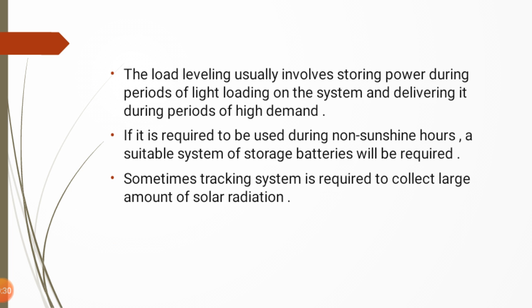Load leveling usually involves storing power during periods of light loading on the system and delivering it during periods of high demand. Demand means requirement. If it is required to be used during non-sunshine hours, a suitable system of storage battery will be required.